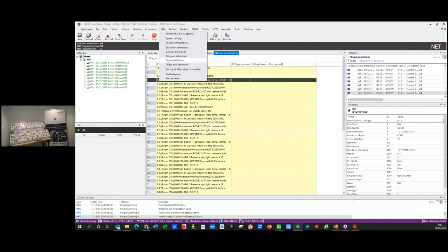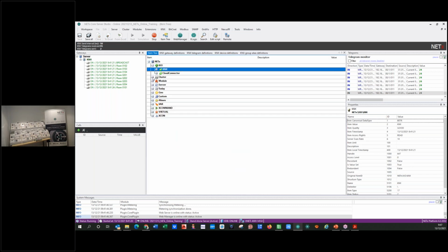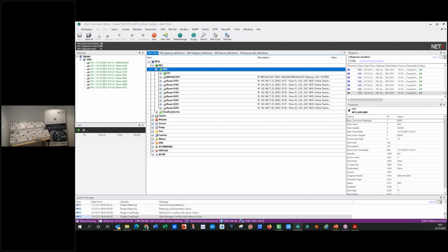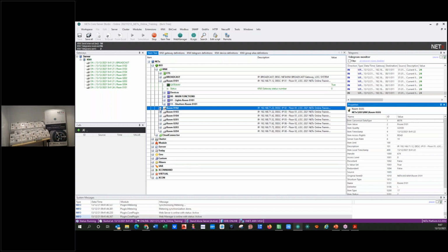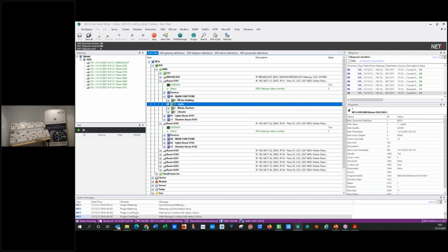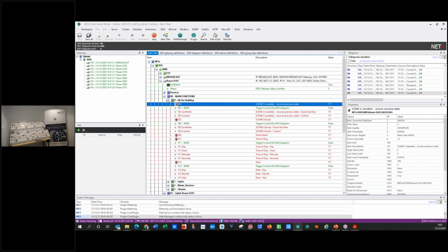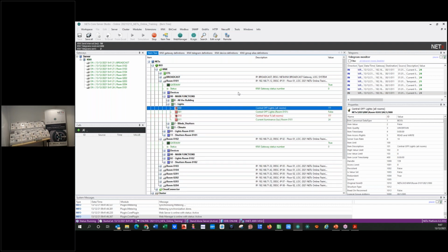The device, okay, the group alias is the name of the main and intermediate group addresses. When you see the item 3, you see that in KNX, inside the XIO, the native drivers, the KNX branch, you have every single gateway with the group addresses, and you have the name of main functions. You know, the blue and the green color is the main and the intermediate group addresses, and the last name is, okay, the name of the group address. It's not complicated. It's the name of the group address, central off lights, whatever.